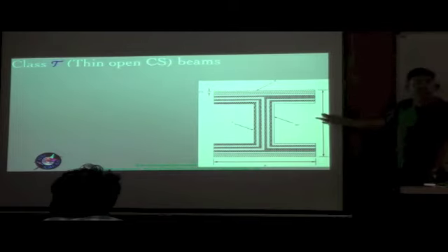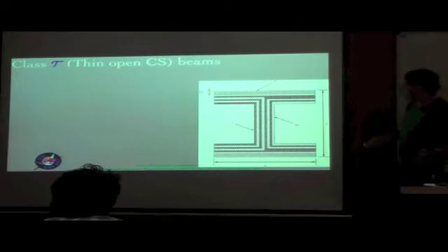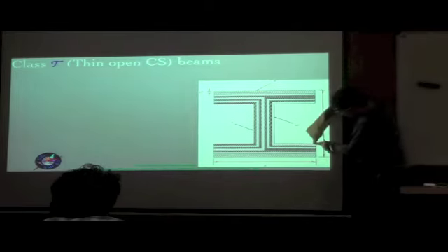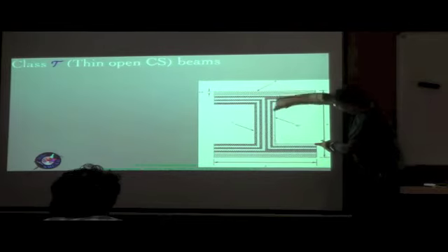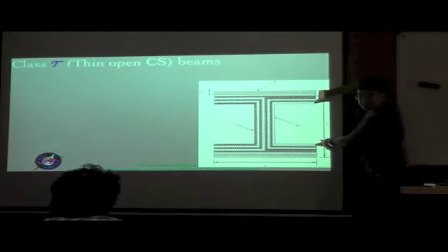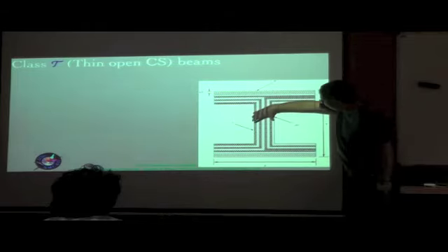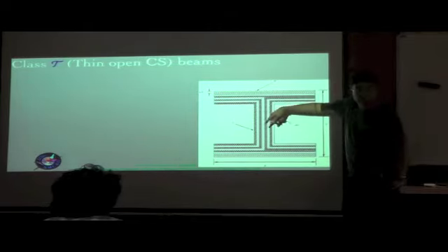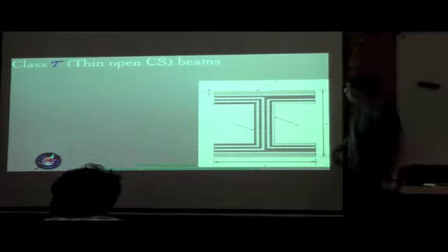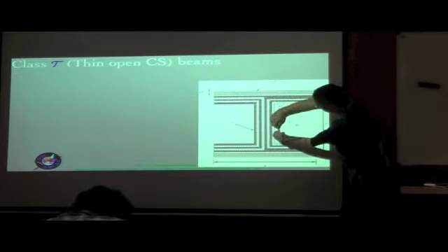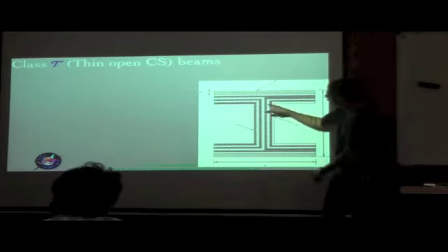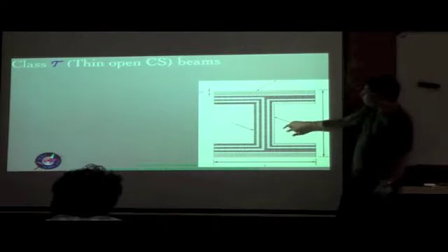Of course, this is not the only way, but in many situations it is made this way, where the same ply goes around and comes here like this, and it is bent around itself. In the web you see only 0/90, in other words, a cross-ply laminate. That cross-ply laminate is bent around itself, and basically you end up with a situation like this.